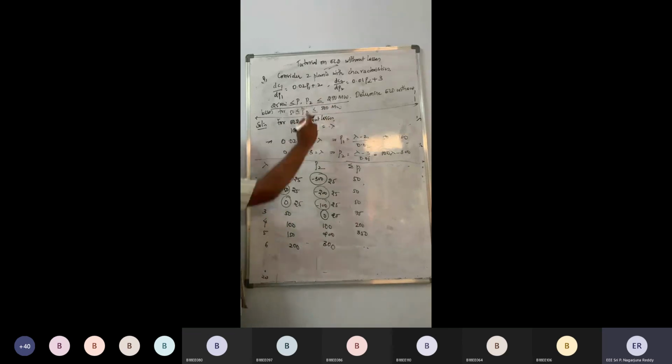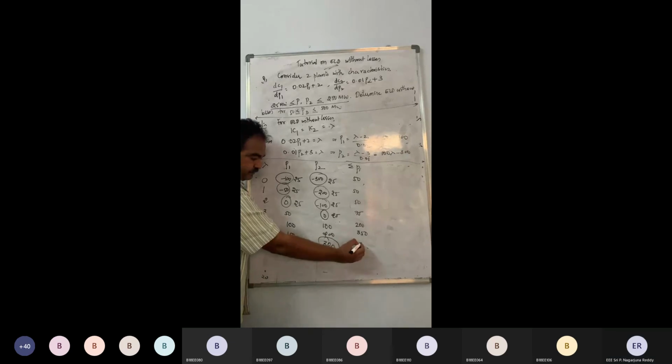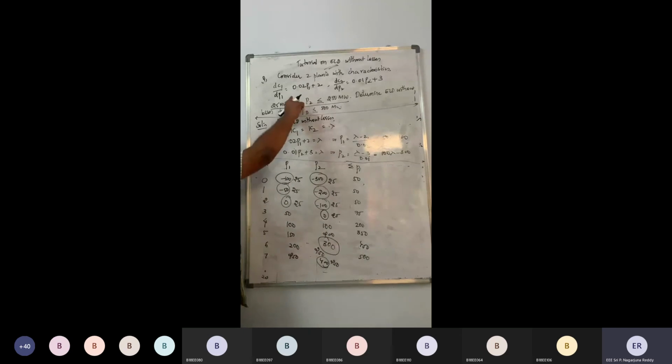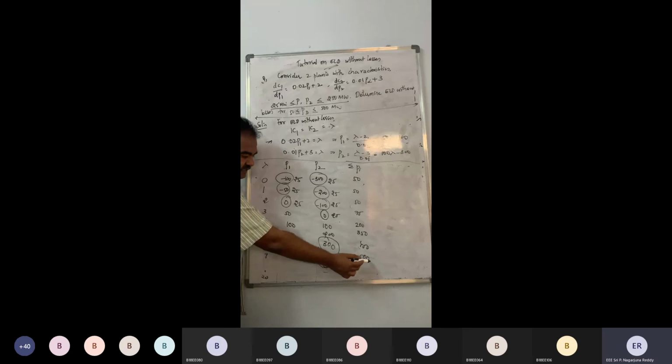But you do have an upper cap also. It states that the maximum generation must be 250 only. So that's why again I am capping it to 250 and making round figure at 450. At 7, 250. This is going to be 400. Again, there will be a capping. And this is my 500. See, check the caps here. Upper generation also cap is there. Lower generation also cap is there. See, my total generation has been reached, and so I will be stopping the block.